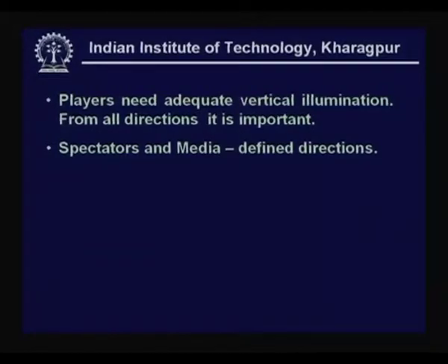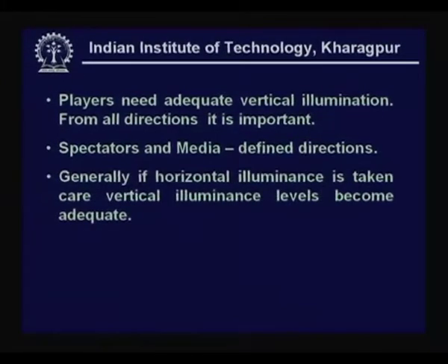The vertical illuminance requirements for the players themselves could be in all directions, so that they are able to really see the movement of the player and the object, whereas spectators, since they are located in a particular stand, or cameras for the media which are located at a specific place, a defined direction is there.